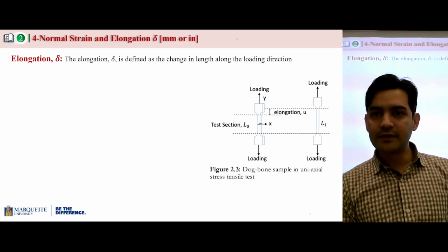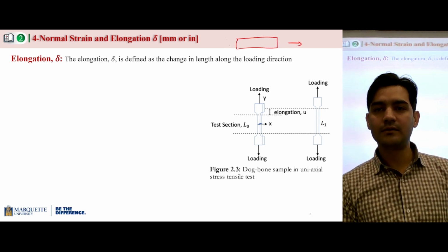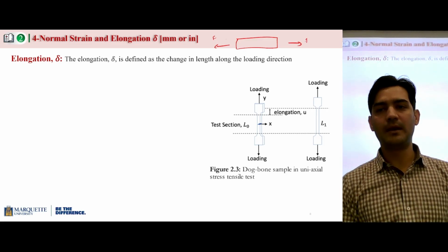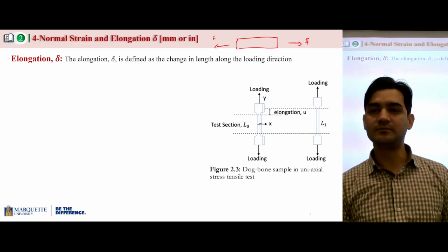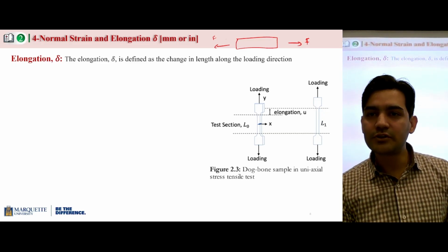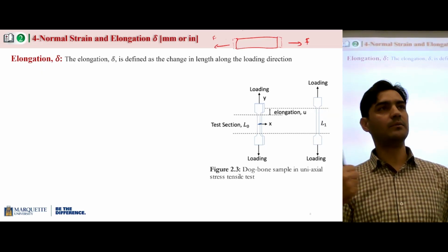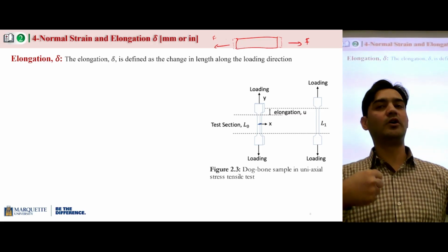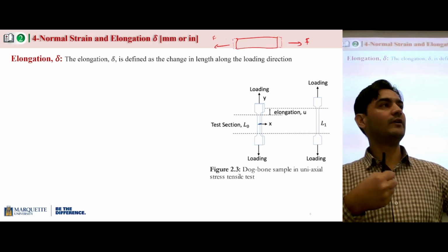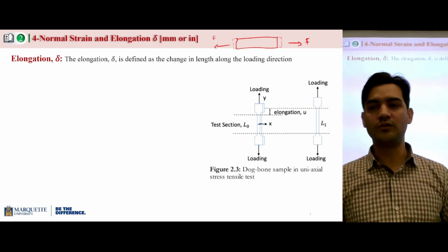As we have discussed before, whenever you apply a force on a member, here I'm applying a tensile force, trying to stretch this member, you're going to see elongation, a stretching of that member, because now it's deformable body mechanics. We cannot assume the body will remain rigid. We also have to figure out how much the body is stretching because of this force.